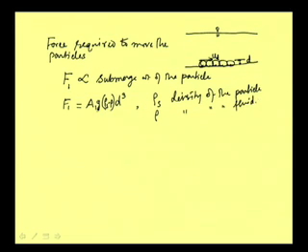So, when we multiply it by g, we are getting unit weight, and that rho s minus rho is why we are getting the submerged unit weight of the particle. This force F1 will be proportional to the submerged unit weight of the particle. So, we can write it like that. Let us keep this as equation 1.